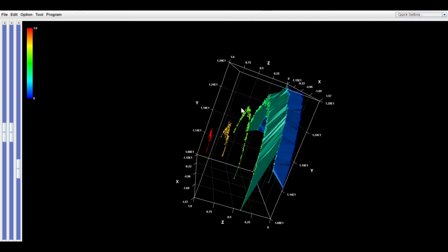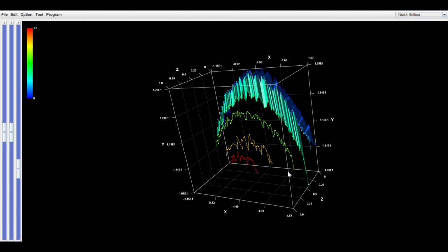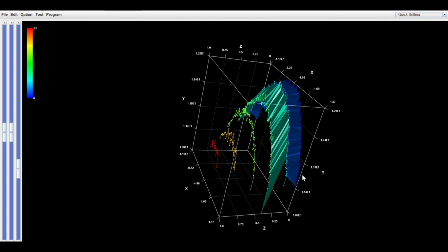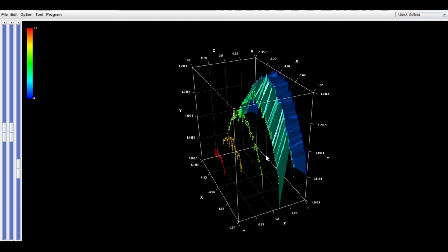Okay, so just to summarize, the 2D OMRON laser profile sensor gives us X and Z values. To add Y, you need an encoder or a robot input that simulates an encoder input, and we take slices at those specific points. We can then import that data into any 3D plotting software, free or paid for, and create a 3D plot and do some renderings with it. We don't provide software for that, but you can get some easy visualization of what's going on with that 2D plot.